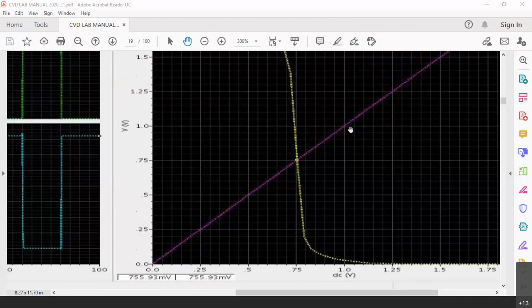So what you can do is, when you physically come to the lab, you remember this particular question and you ask us. I'll tell you how to change the device dimensions in the tool. By pressing Q, you can go to the P MOSFET property and you can change the W. Instead of 2 micrometer, you can increase it. 2 micrometer into 2.2 is 4.4 micrometer. After that, save your design, again plot the curve and see the changes. So that is possible.